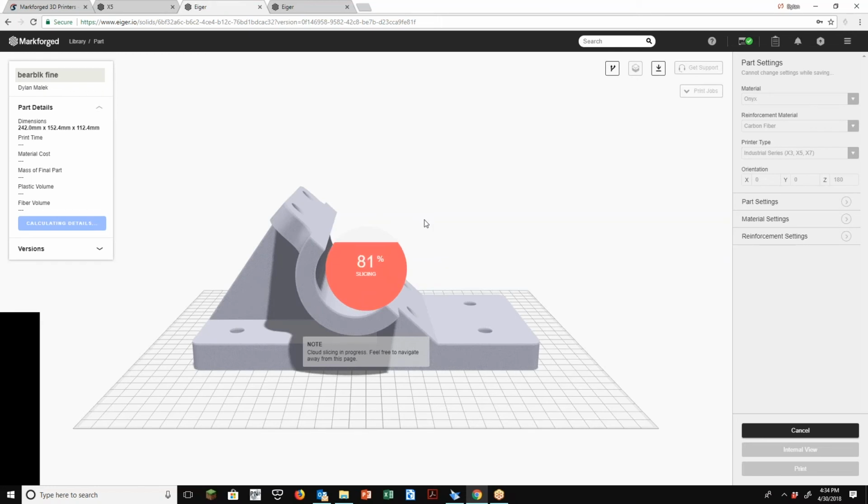All right, so once you're doing the carbon fiber, pretty much any of these reinforcement continuous filaments, you have to get a little tricky sometimes depending on the orientation that you want the strength laid in. Again, because we're laying it planar to the base and it moves in the Z direction, all the layers itself would have it in this direction.